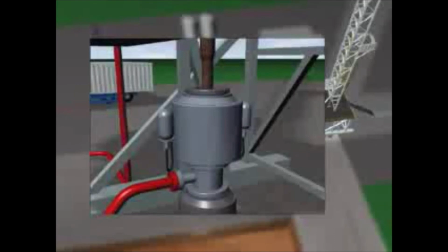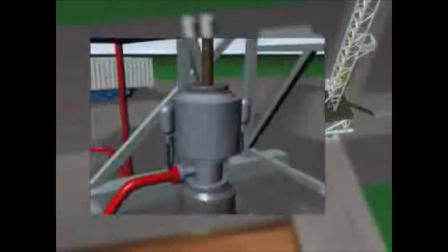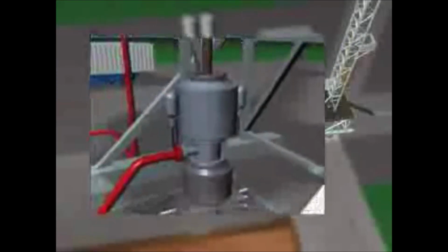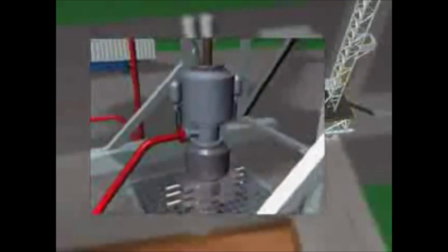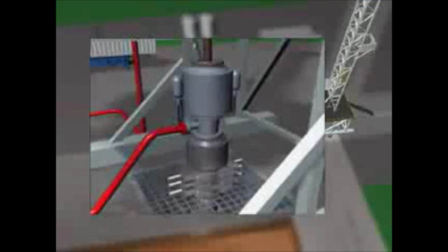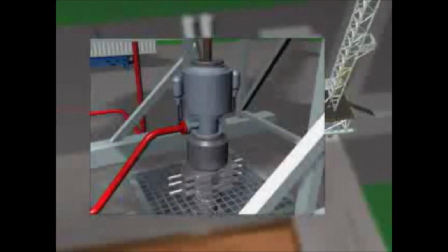The return fluid from the well is diverted by a rotating control head to the surface separation equipment. The control head seals around the drill pipe while allowing the pipe to move in and out of the well and rotate. In some cases, a snubbing unit needs to be installed to allow movement of the drill pipe in and out of the well under pressure. Moving slips on the snubbing unit grip the pipe and push or pull it against the upward force in a controlled manner.